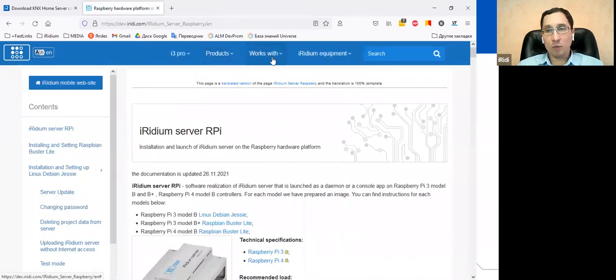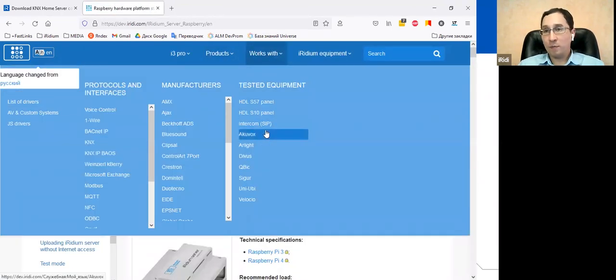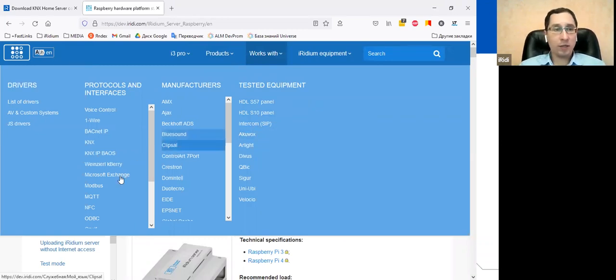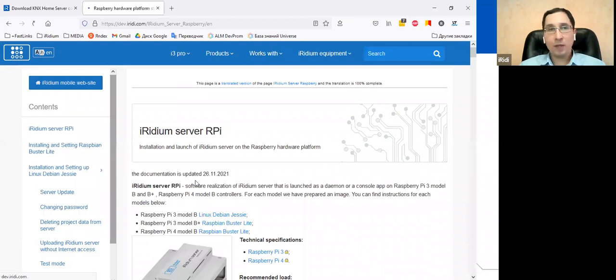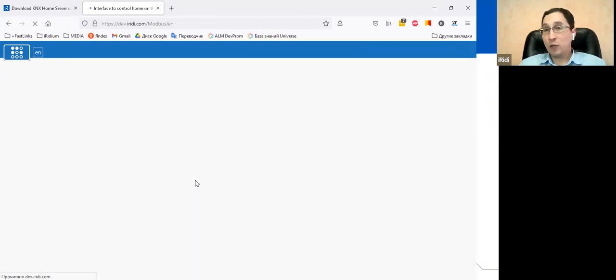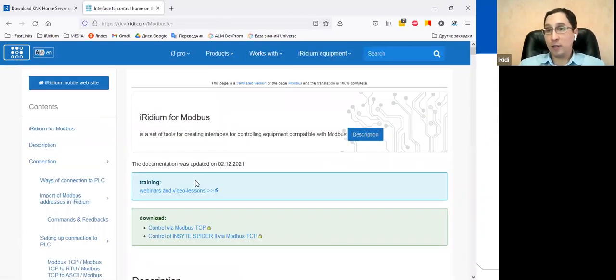And sometimes if you have work on a site with Modbus hardware, our integrators ask us in support, "Wow, I have a very big freeze in the Modbus driver. What is that?" And actually, in 40% of cases, it was about one more register in Modbus which can be used.